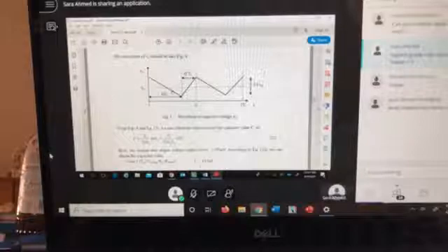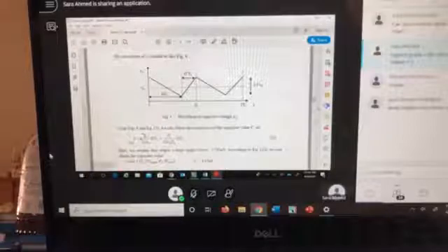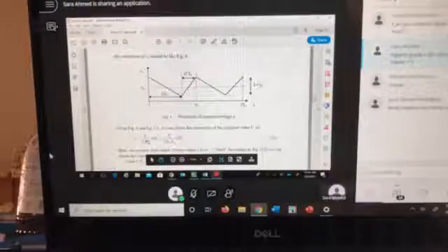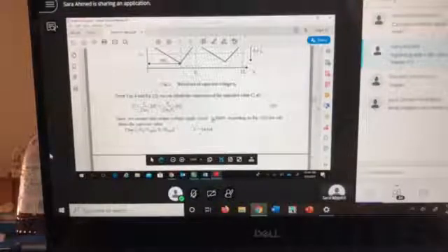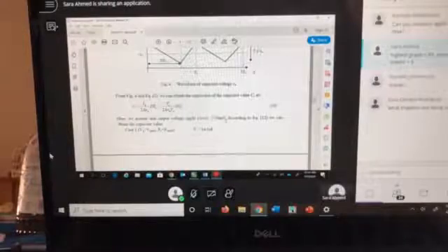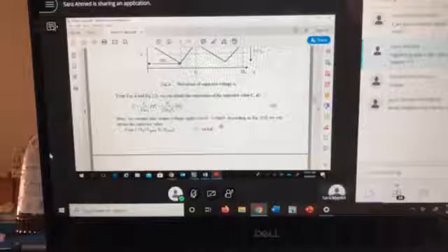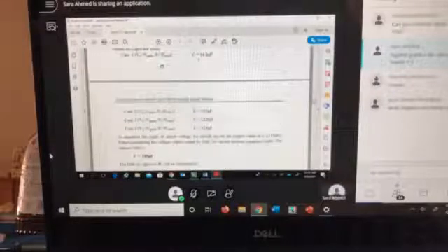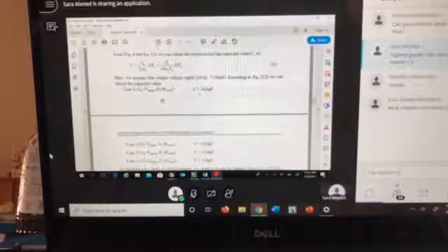So now I can do the exact same thing. I can choose either DTS or D prime T of S, and that becomes your I of C divided by C is equal to 2 delta V out, and delta V out is given to you. We actually were given that delta V out has to be less than or equal to 50 millivolts. So I just chose the maximum, which is 50 millivolts, and calculated based on this. So again, what are we gonna have? We're gonna have 4 values for the capacitance.